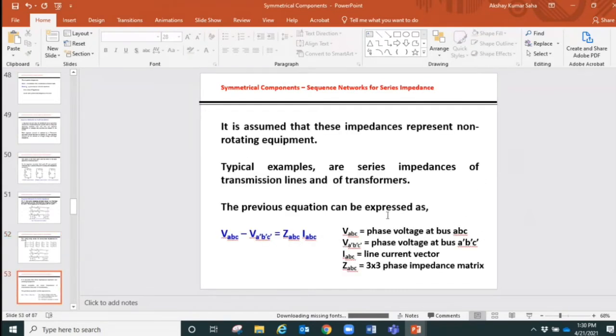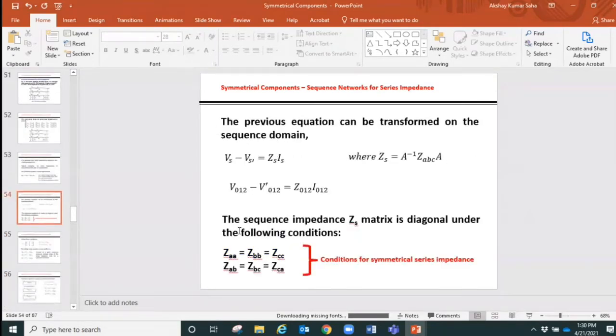phases. So if we go there to what we did, this is the phase voltage and it's actually the product of the phase impedance and the phase currents. So ZABC and IABC are the phase currents. Then we will do that symmetrical component analysis. We knew that formula. How do we go from actual phase voltages, actual phase currents to positive sequence, negative sequence, and zero sequence components?